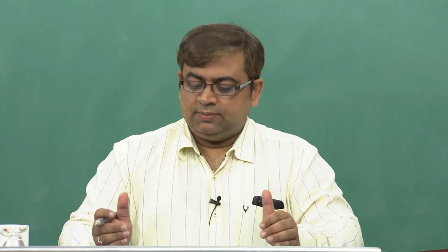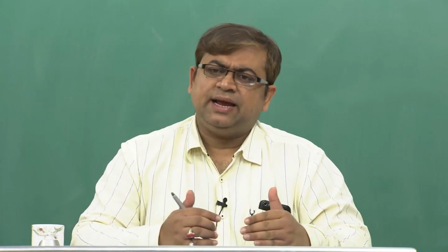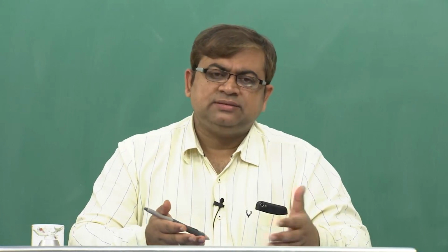At that point the silicon and the glass are heated up because of the anode. You heat it up to a temperature where there is fusion bonding between the glass and silicon, but in the absence of the field. So, that becomes a permanent, irreversible bonding, and it results in thin cover slips getting permanently bonded to, let us say, silicon substrates which are highly structured, or have printed electronics on the silicon.